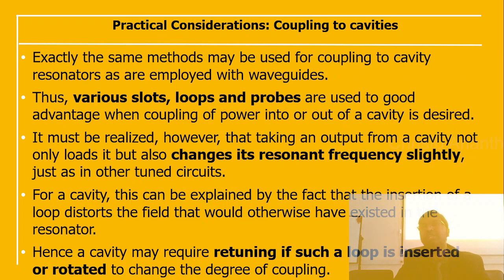So the same methods you can use for coupling to the cavity resonators are actually employed with waveguides. Okay, so various slots, loops, and probes are used to good advantage when coupling of the power into or out of a cavity is required. So it must be realized that taking the output of the cavity not only loads it but also changes it, varying its resonant frequency, just like other tuned circuits.